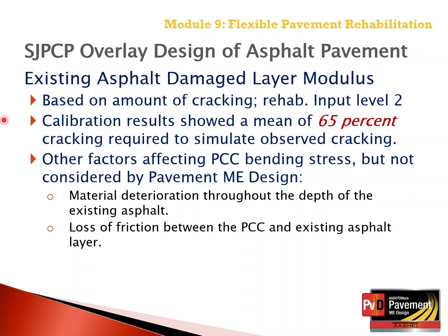But the important point is 65% fatigue cracking is used to characterize the existing asphalt pavement when short jointed plain concrete pavement overlays are used above flexible or asphalt pavement.